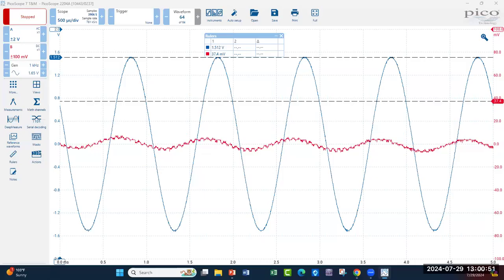So that's another good troubleshooting step, and that is what happened to our waveform. Our channel A waveform, 2 volts per division, I'm coming in at 1.52. My channel B waveform is really an ugly looking thing. So we need to check our connections on the board. As it turns out, in my last frame of the board, I had pulled the channel B yellow jumper and planted it somewhere else on the board other than point C. So I'm going to reconnect this at point C and now run this.